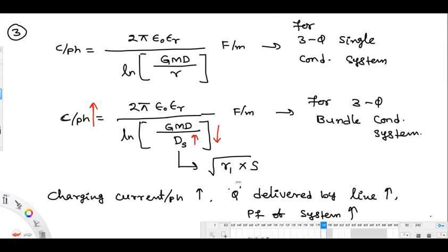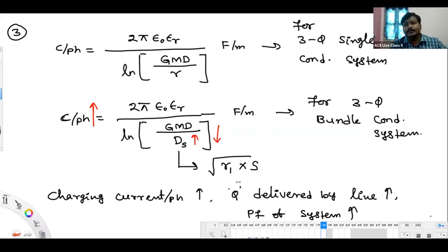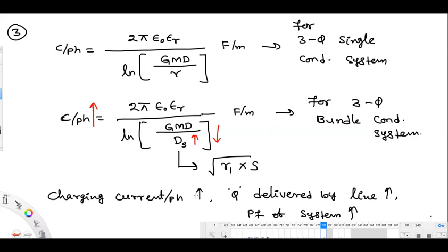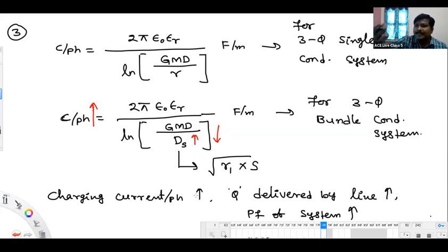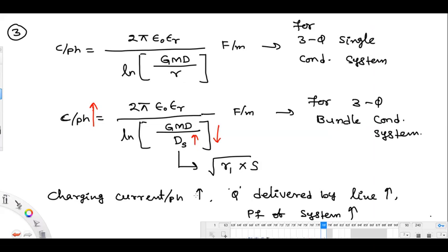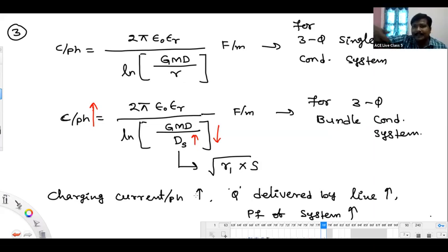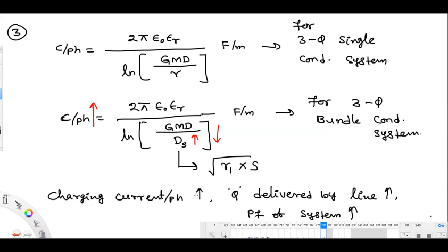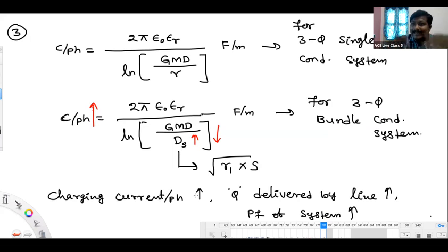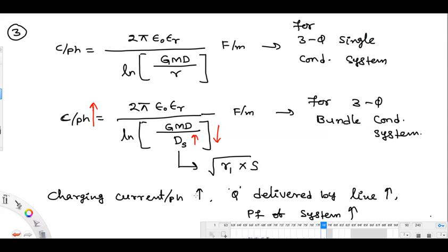Good morning, sir. Good morning, Anil. Tell me. Sir, you told that the conductors can be arranged in different manners, the RYB diagram, arranged in sequence or alternate? The alternator might be giving RYB, but they change that sequence in the transmission line. There is no issue with that. Ultimately, their intention is that while reaching the grid, it should be clear which is the R phase, which is the Y phase, and which is the B phase. Because in the grid, many other systems are interconnected, right? So whatever incoming line we have, that phase sequence should be synchronized with the other phase sequences. Yes, sir. For that purpose, they give that indication on the tower.